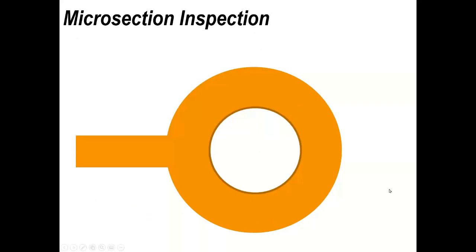Now, whenever I do microsections of plated through holes, and you've seen a failure like the one I've just described, I normally section the board again because there is a benefit: you can see further information. So what I do is take a microsection.